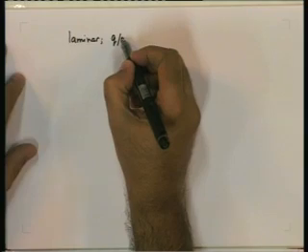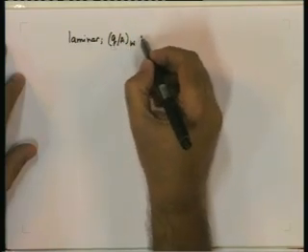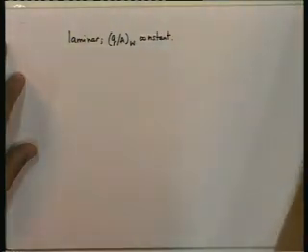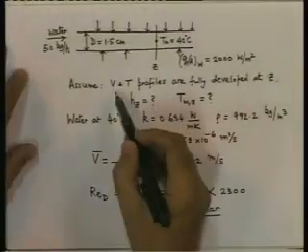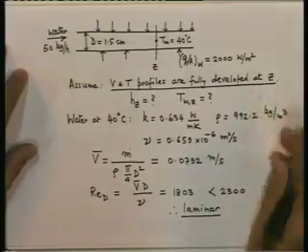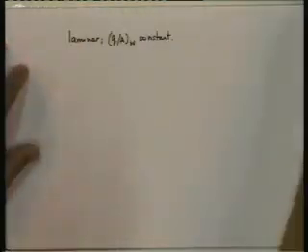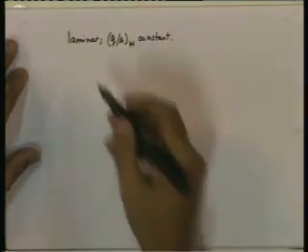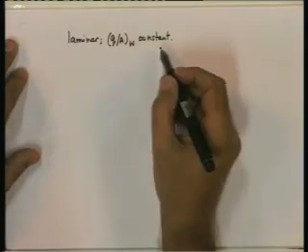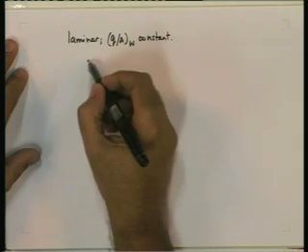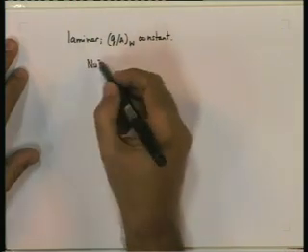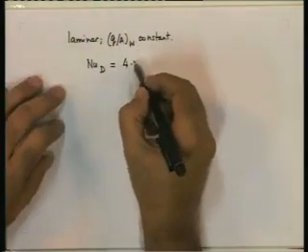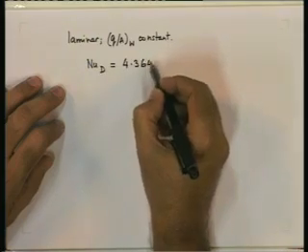We have heat flux uniform. We have already assumed fully developed velocity and temperature profiles, and hence we can use the result for the fully developed constant heat flux laminar flow situation in a circular tube, which will give us the local Nusselt number as 4.364.